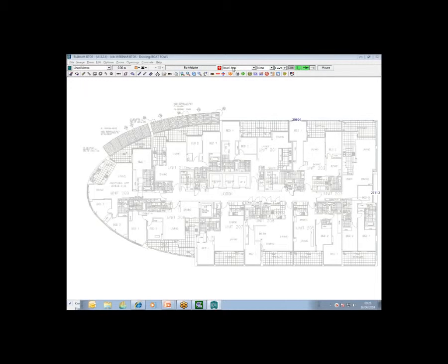What I then need to do is use my zoom function to zoom in on the section of the drawing that I want to do a takeoff on. Now, I want to show here how curved work can be done. So I'm going to take off this lineal length here. I'm just going to click on the zoom in on section of a plan, come down, click, hold, drag,